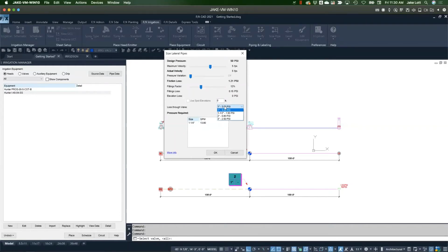So just like we sort of did here with that speed of water and the amount of flow, the valve has a certain amount of flow that it can feed while producing some type of friction loss through that valve itself, pressure loss through the valve. So we can now make the determination, does it make sense to keep a 1-inch valve, or does it make sense to up it and only lose, basically cut that loss in half?